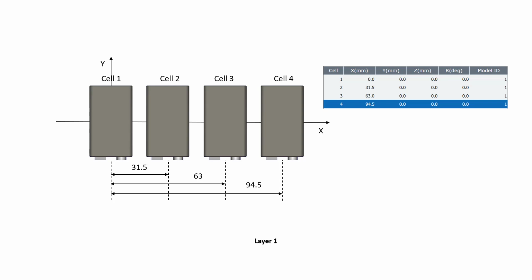We need to specify the origin of the tray. The origin can be in any arbitrary position, but normally it's going to be a position where it's easy or more convenient to teach. In our case, we're going to select the tray origin on the center of the part located on the first cell, as we can see here on this illustration. And then we're going to specify the X direction on the same direction as the tracking frame. And we're going to position the rest of the cells on the X direction of the tray.